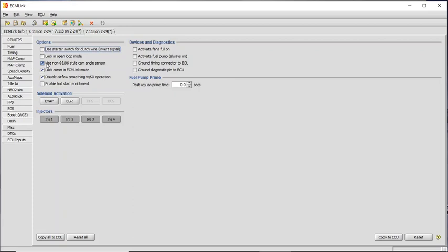If you have any other of these cam angle sensors and you don't swap your firing order around and you can't get it to run, well, there you go. That's probably your problem. You didn't swap the firing order around. That's what you'll need to do. But that really should be the only thing that you may need in this particular one to get it fired up and running.